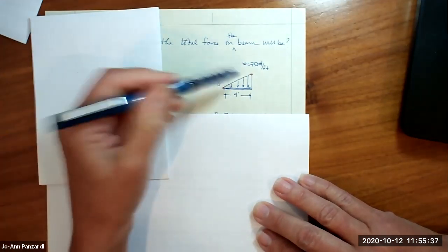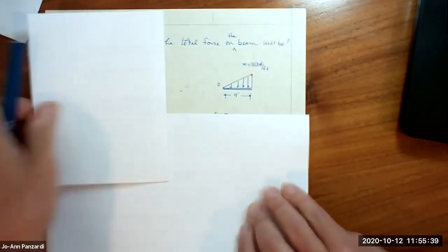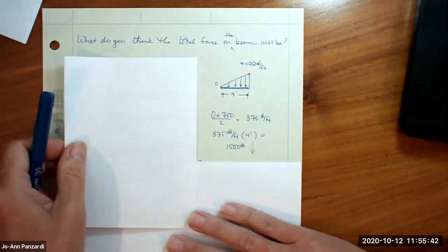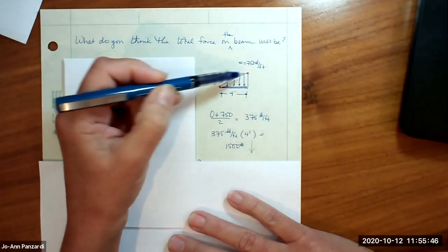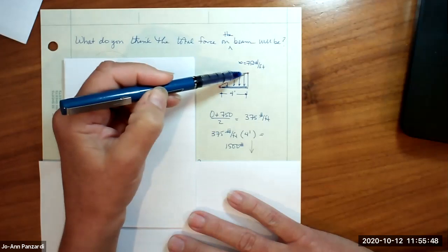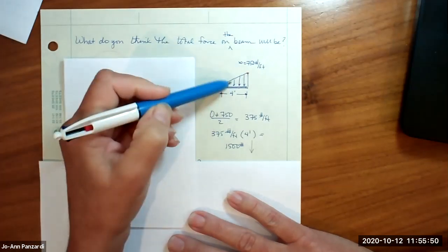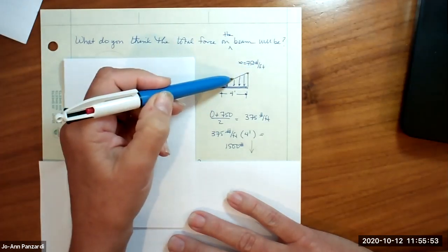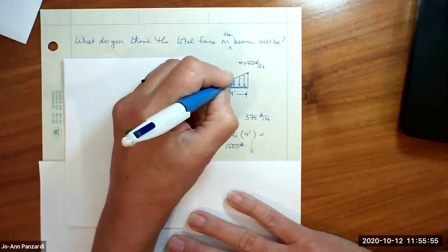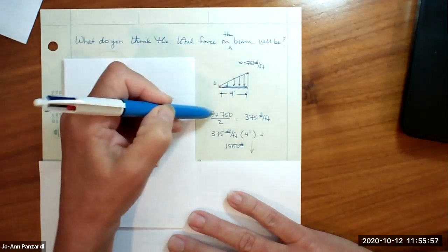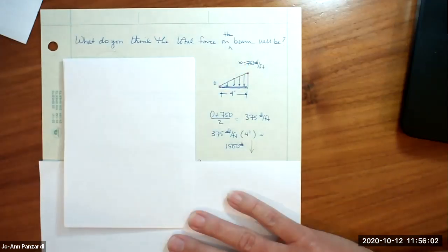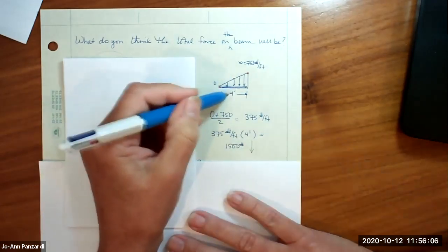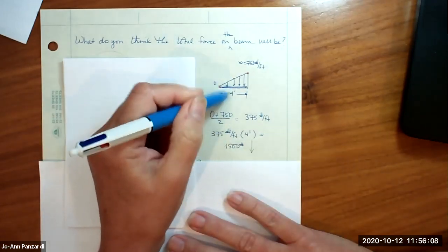Okay, so it's 750 here. And if you said this, you are correct. We're looking at what is transpiring over this. If we average the pounds per foot over this whole section in the center, it's 0 plus 750 divided by 2, and that gives us 375 pounds per foot in the center. And that is equal to being supplied over the full length.